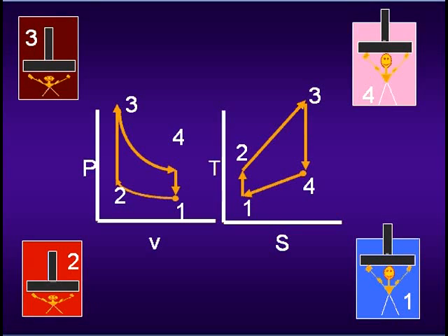When you ignite the gas, in the Otto cycle we think of that being done at constant volume. It happens very fast, and the heat is added almost instantaneously, and the temperature shoots up, and when the temperature shoots up, the pressure goes up at constant volume, and then as you expand it, the pressure drops and the volume increases, and then you start all over again.